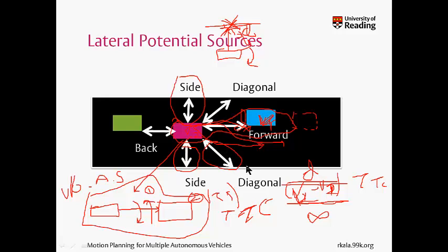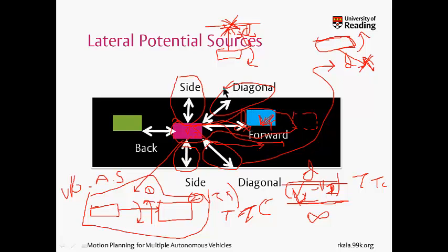And let me take this case. You are the vehicle out here. After this, there is some obstacle. I still do not know what it is. There is some obstacle over here. So you obviously take the counterclockwise turn, or you take the left turn by something that is, again, inversely proportional to the distance. If distance is very less, then you turn very much. If the distance is very much, you turn very less. And this case would be opposite.